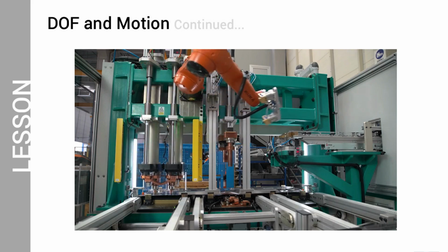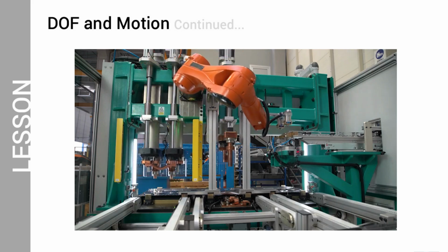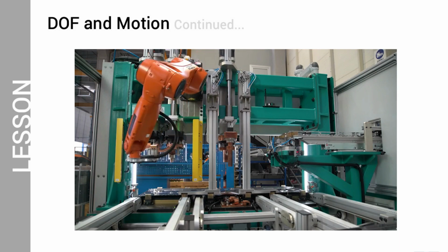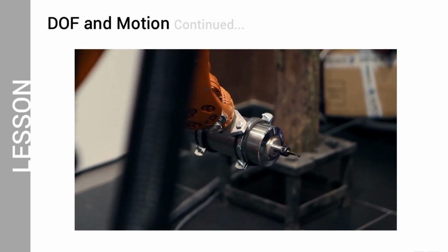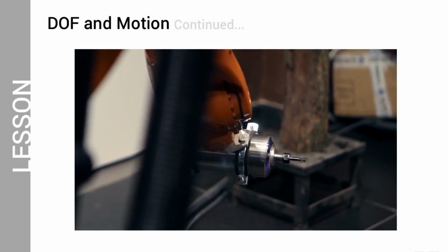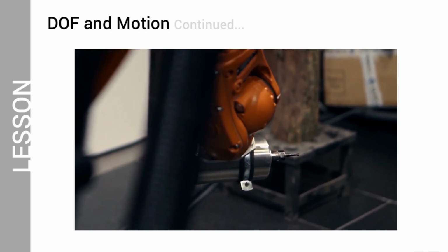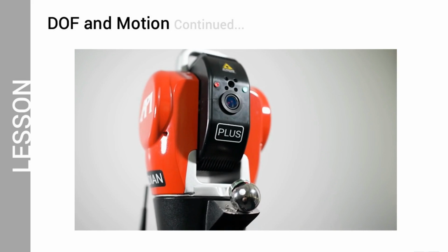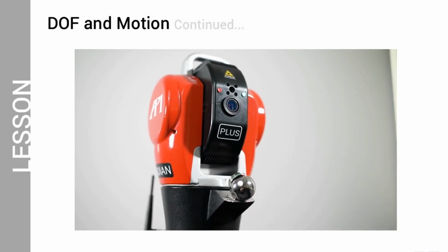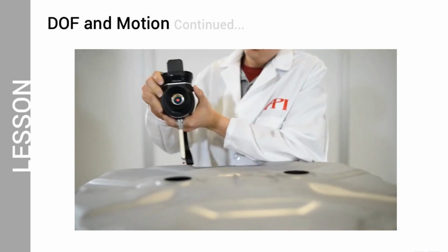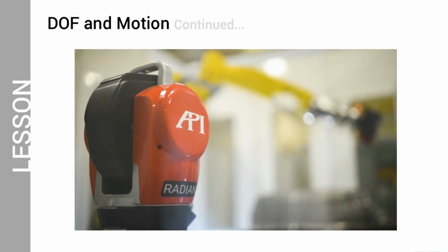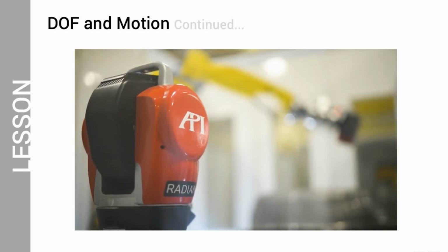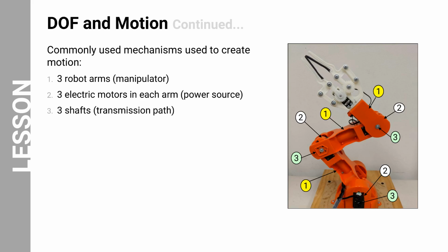And in manufacturing, each joint and the 6 potential degrees of freedom that come with it represents a value that must be captured and tracked to ensure accuracy. This makes having a laser tracker that can capture all 6 DOF for the probe or sensor measuring a part essential in today's automated manufacturing environments. After understanding DOF, we can see how a part can move in different ways, translating along and rotating around the X, Y, and Z axes.